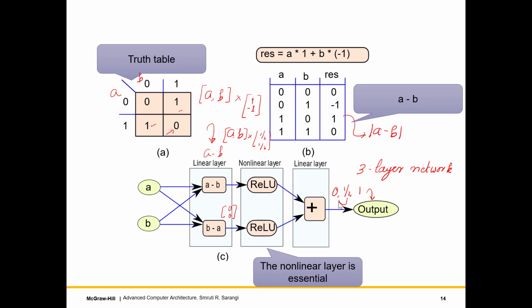I mean, setting this over here, but we can just say that we will look at the most significant bit after the decimal point, and if that is 1, we will interpret the output to be 1, otherwise we'll interpret it to be a 0, which basically means that this becomes equal to an AND gate. Only when A and B are 1, the final output will be 1, otherwise we will interpret the final output to be a 0.